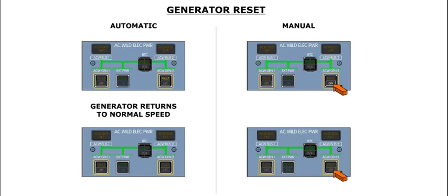If the fault was due to an NP overspeed that lasts less than 3 seconds, or if it was due to a generator underspeed, the generator will reset itself automatically. For any other faults, the generator can only be reset by cycling the affected generator push button to off and then back in.